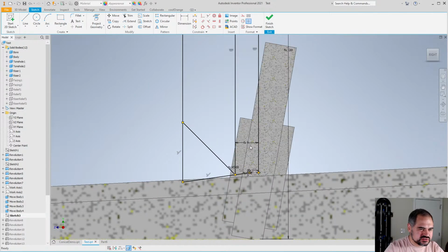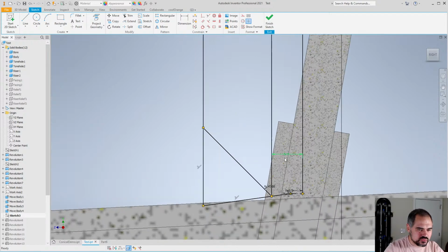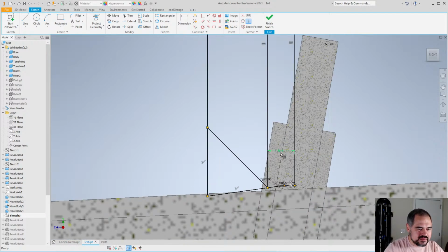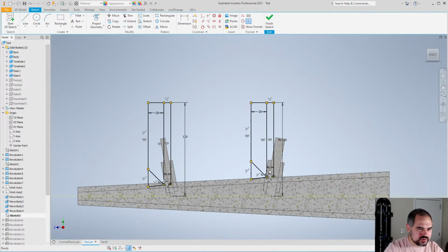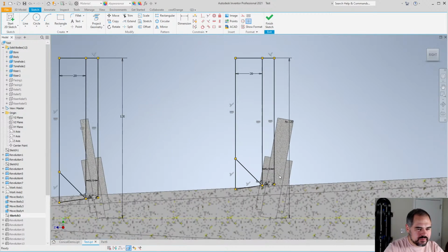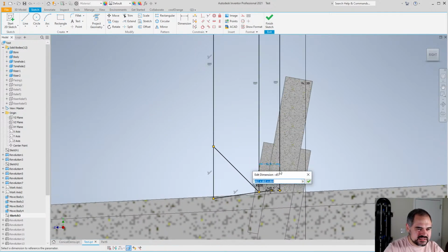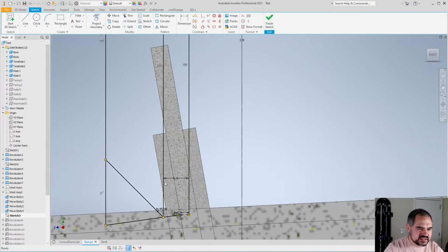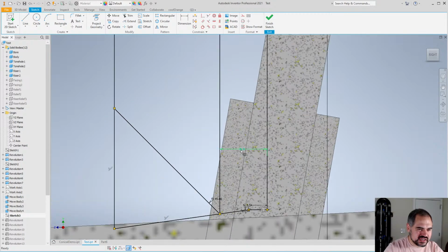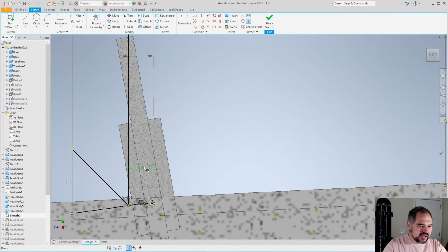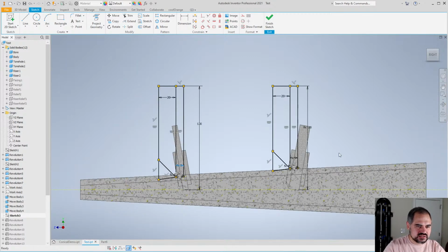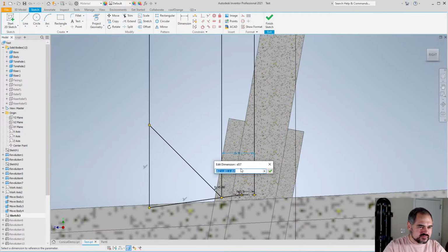When I copied the second relief, I forgot to change the parameters. When you copy and paste a sketch, it by default uses the parameters from the first sketch. Right now, I have this sketch set to tonehole 1 radius plus tonehole pad overhang plus tonehole pad clearance. It's just dumbly setting all of those parameters the same.